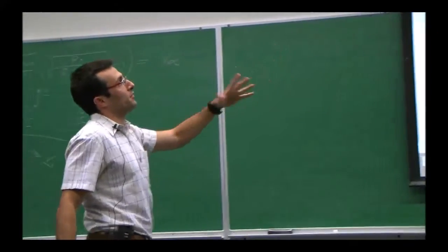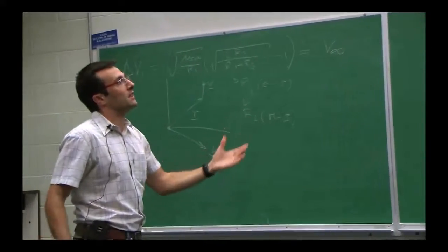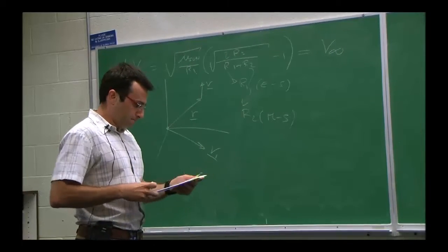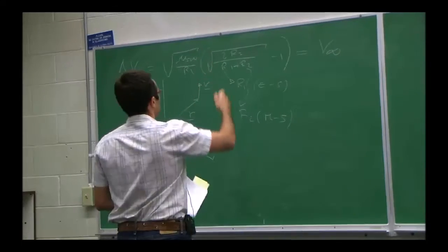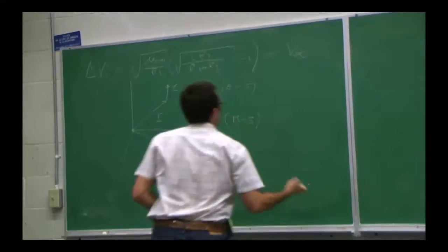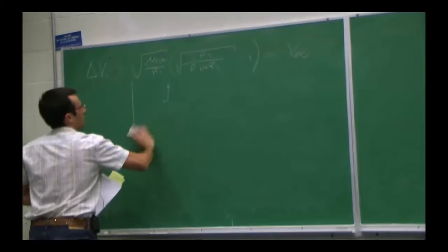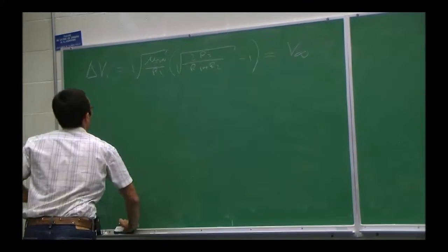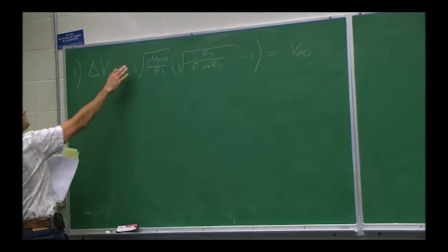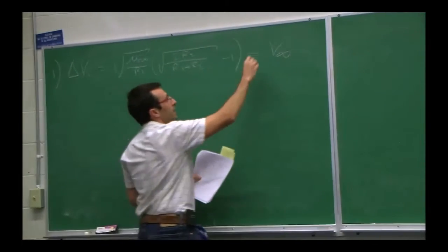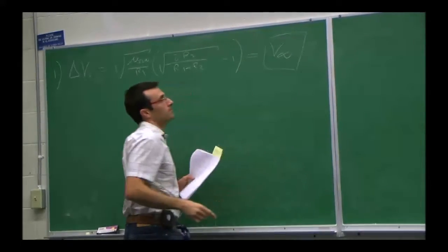You're solving the problem in a different way. You are given that value. So let me see. Well, that would be the first step, right? The delta V. If you want to solve for what you need to do to leave the planet, this is step 1. Compute the delta V Hohmann and know that that has to be your V infinity.